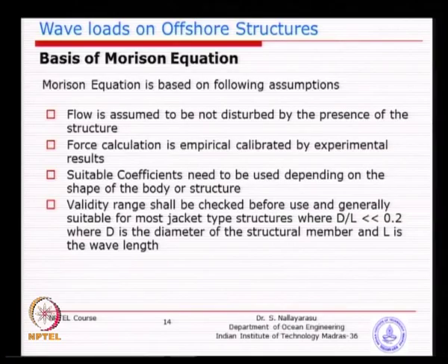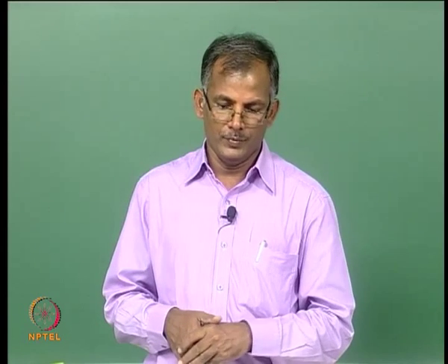complex. Without such studies, trying to simulate by pure numerical means or by analytical means, you may not be able to do so. If you can do so by making some simplified assumptions and then correct those results by comparison with the experimental studies, that is a practice, because as I mentioned, fluid structure interaction problem is always complex, especially because of the viscous effects, and that is why back in the 1950s Morison proposed such a nice and simple formula, which even today we use to design complex structures for offshore applications.